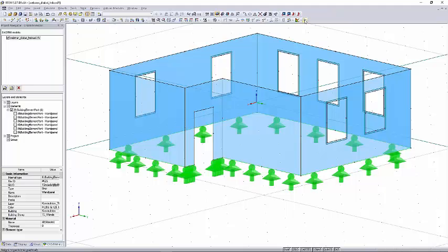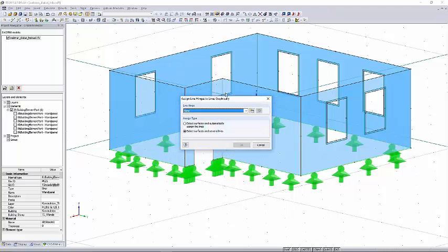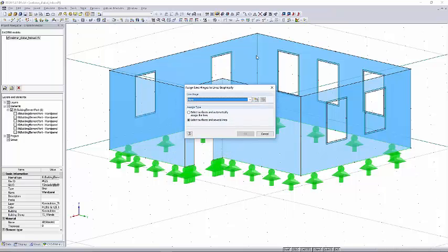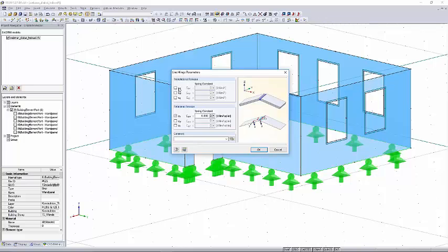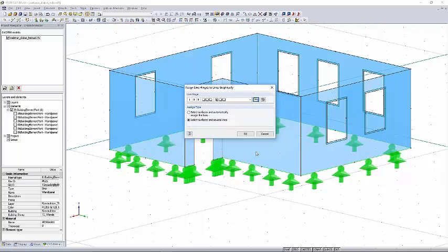Then the next step is that I will add line hinges to the structure, because as I said, here in the corners it's moment stiff. It's also possible to define here some slip in X and Y direction, usually on a CLT plate, but as I said, this is done in a separate webinar where I also mention how to generate the stiffness in all the other parts of this.